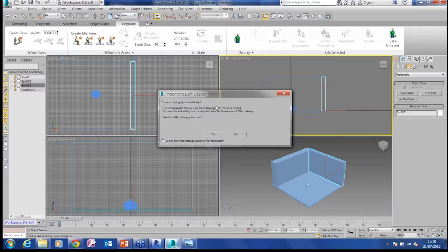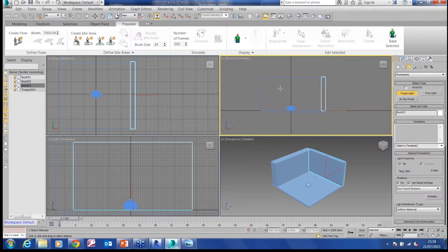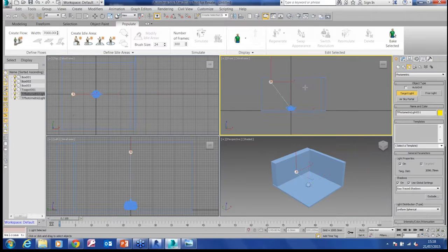What we also have in here is tools within 3ds Max to do lighting analysis as well. So we can actually start to put light meters down, and then we can calculate our exact lighting conditions within our scene. So this is going to be Fairwood. I'd like to change that now. So I'm going to enable my photographic exposure control, and I'm just going to put a couple of lights in here.